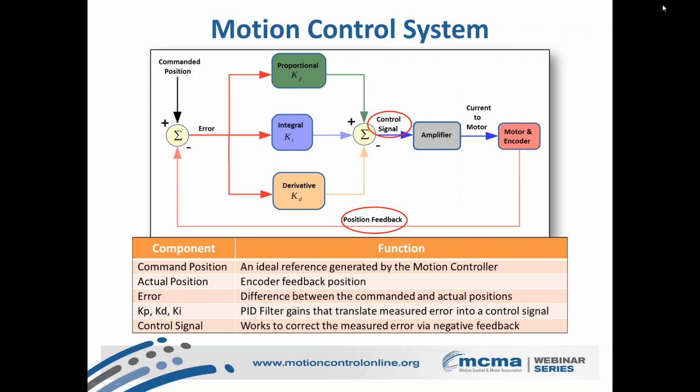Downsides is that each node, so let's say each amplifier and motor combination or I/O module at the end of this communication, is going to be costlier than a standard analog amplifier, because you have the amplifier and I/O hardware, plus there's a dedicated microcontroller on each one of these nodes whose sole purpose is to take this communication and parse it into necessary motion commands, motion data. And so there is increased cost associated with that.